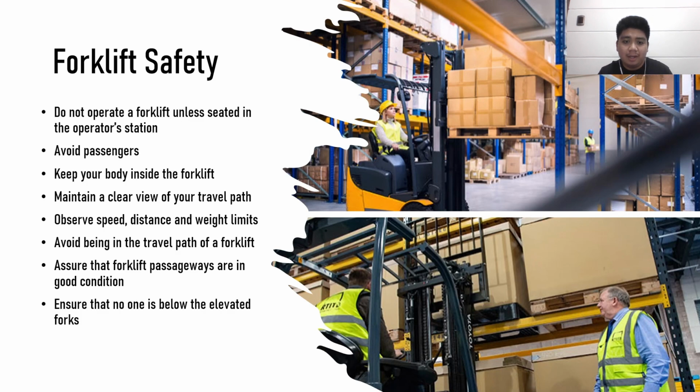Second, never allow passengers unless the forklift was designed for a passenger. It is also not suggested to let anyone ride the forks of a forklift. Third, do not put any part of your body between the uprights of the mast or, when traveling, outside of the forklift frame. Necessarily, ensure that your whole body is safely inside the forklift.